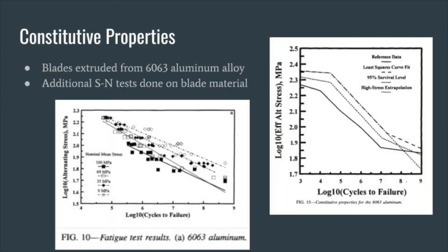Now, in order to utilize a stress-based fatigue life approach using Miner's rule, an SN diagram is necessary. This is an issue because the available SN data typically has very little information on cycles up to 1 billion, which is what wind turbines are meant to withstand. Due to this issue, material fatigue properties were derived from extensive coupon test programs.